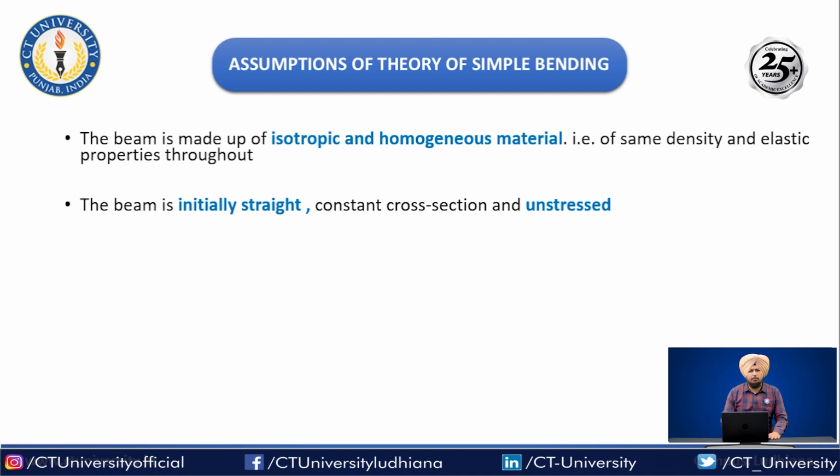The second assumption is that the beam is initially straight. There might be some manufacturing defects, or some initial deflections due to manufacturing, installation, or assembly, but for our analysis purpose we are assuming that the beam is initially straight, and the cross section is constant.